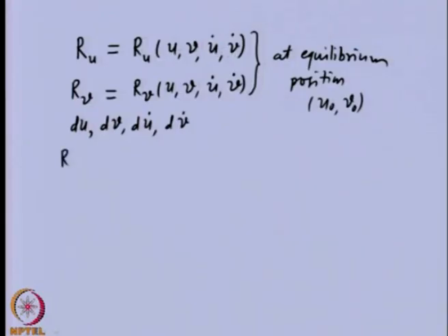So, the fluid film force will now be written as follows. We expect this fluid film force to change because of this disturbance. This particular one is in the u direction; similarly, the variation will be there in the v direction also. This function we can expand using Taylor series expansion.